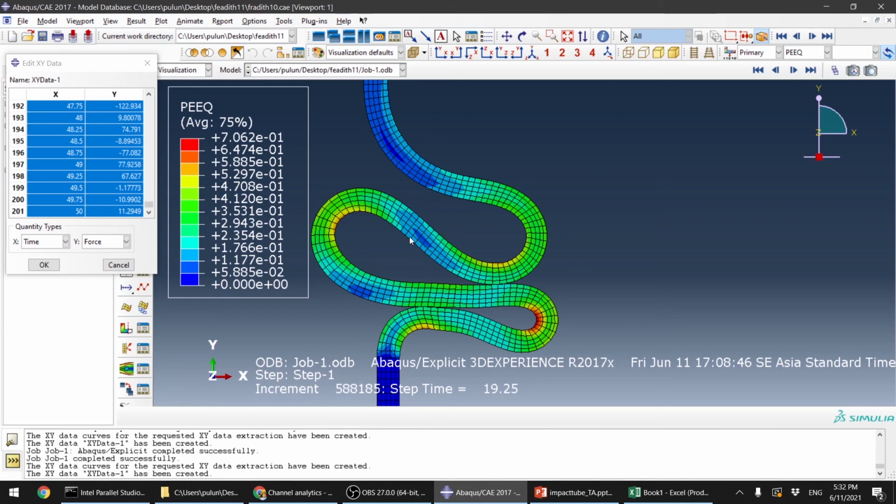So we need to give several curves. So what we just did today, we gave several data for various strain rates. So Abaqus will interpolate data between them, right? So I think it's enough for today. I hope it's useful for you. It's giving you more experience on how to deal with rate dependent data.